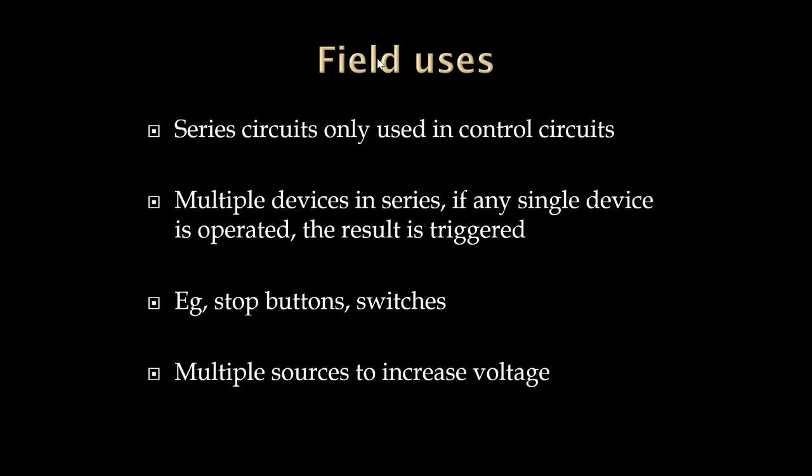The other place that I'm going to use a series circuit a lot is multiple sources. So multiple voltage sources: if I connect them so they all have the same polarity, I'm going to increase the voltage. Okay, so batteries, we use that all the time in remote controls. I put more than one battery in it. Those batteries are connected with the plus to the minus. So that is an increase in the voltage. So it bumps the voltage up.